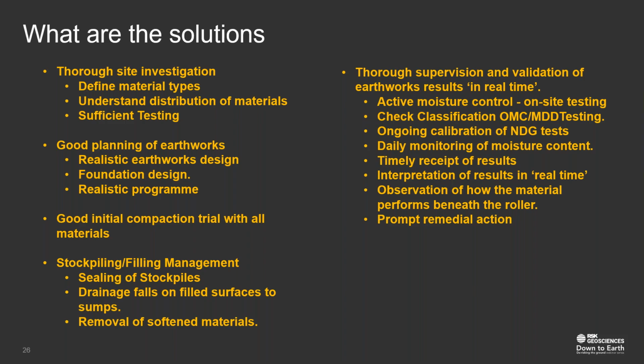Don't let them drift for two or three weeks, because you may then go back, look at the results and find, actually, we had a problem with that layer. There's an anomalous result there. We're getting loads of very low readings, but that layer is now actually three or four layers down. It then becomes very expensive to do any remedial work on it.